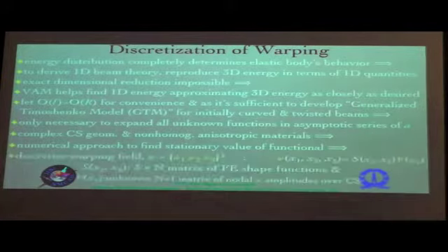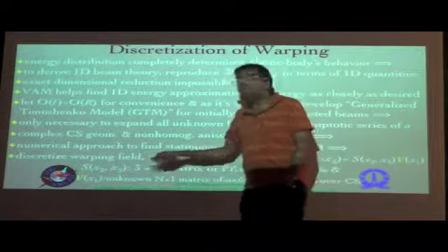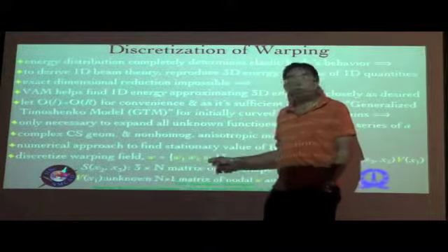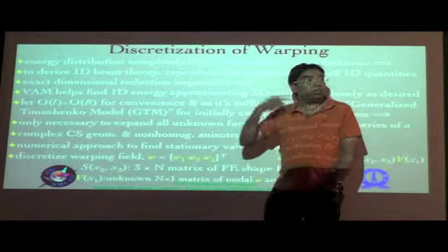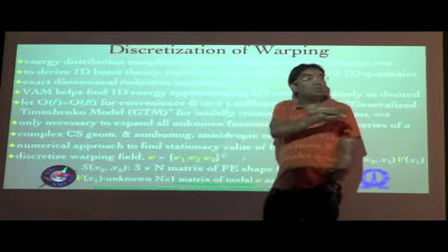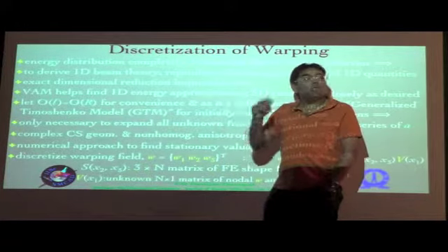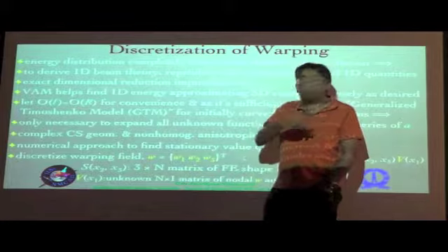In all other more generic situations, like the airfoil cross section that we talked about, for example, we need this numerical approach. So what we do is, we know that the unknown quantity is the warping field, that is W1, W2, W3, and this, recollect, is along the small bi direction, though when expressed in terms of the position vector, it would involve the big bi's or big ti's because of the pullback that we are basically doing there, right?